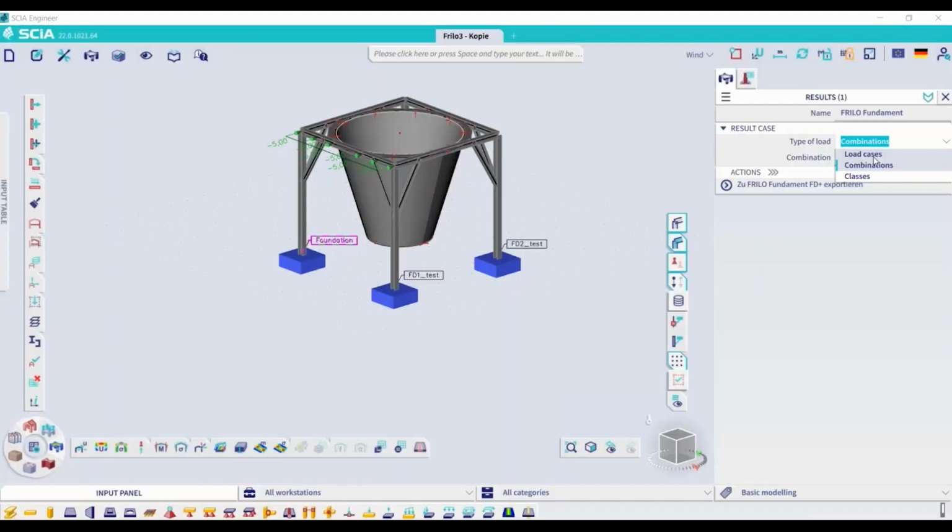So in that case, you might hand over just single load cases on a characteristic base, because in that case the combinations can be done on the foundation side itself. Because, for example, if the calculation is linear, additional internal forces according to theory of second order are not taken into account.